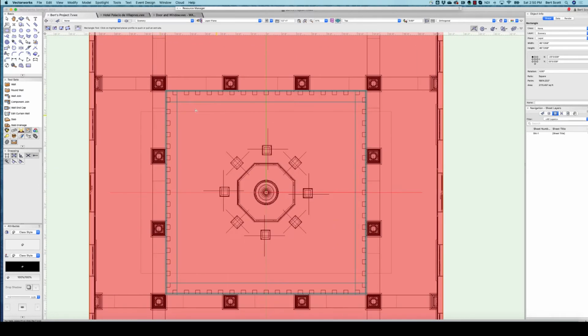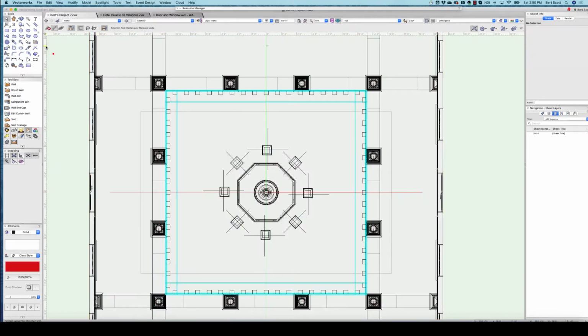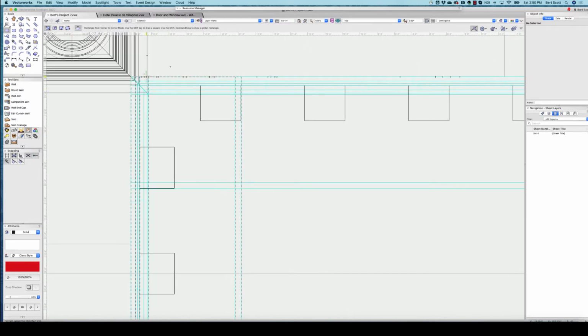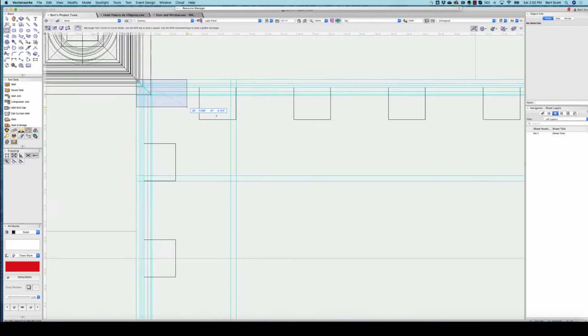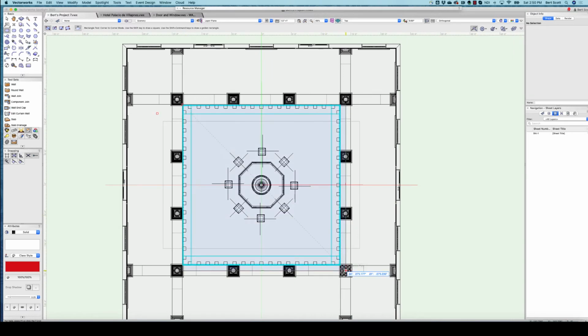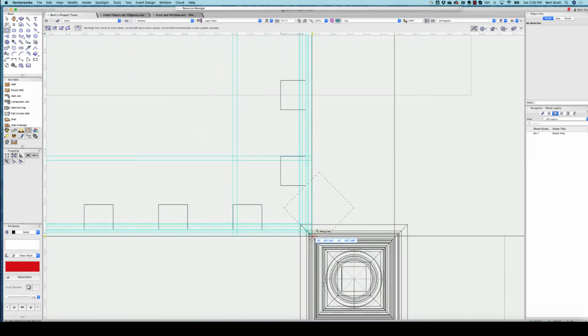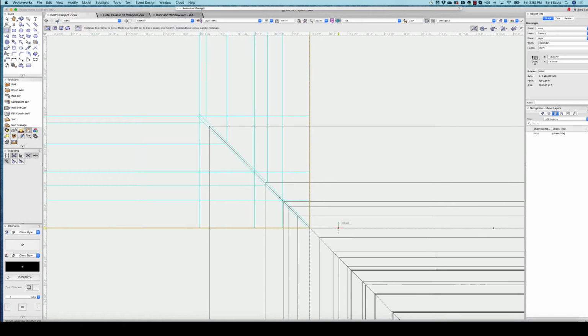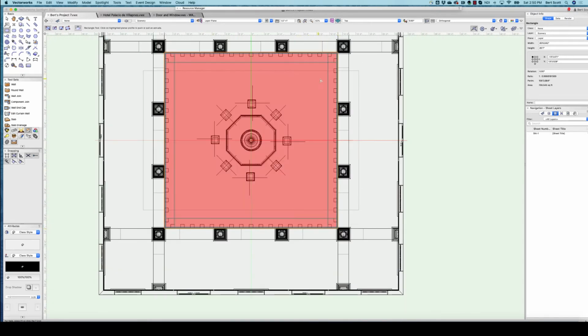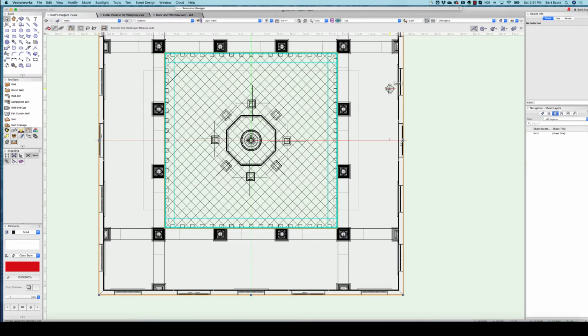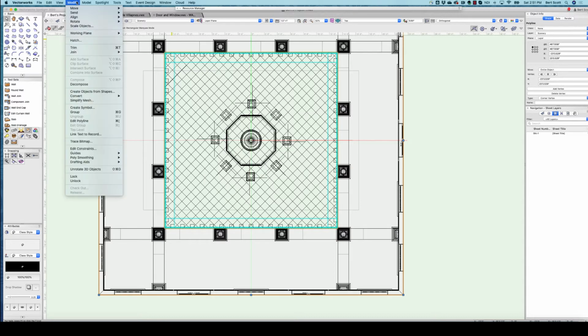and then the second one, and I had to click off it and go back to the right, otherwise it was in auto extrude mode and it was turning red, and I don't need that. So then the next one is I'm gonna cover this portion that incorporates all of the molding that was on the arches. And then I'm going to take both of these rectangles and do a clip surface and then hit delete. And then this one I'm going to